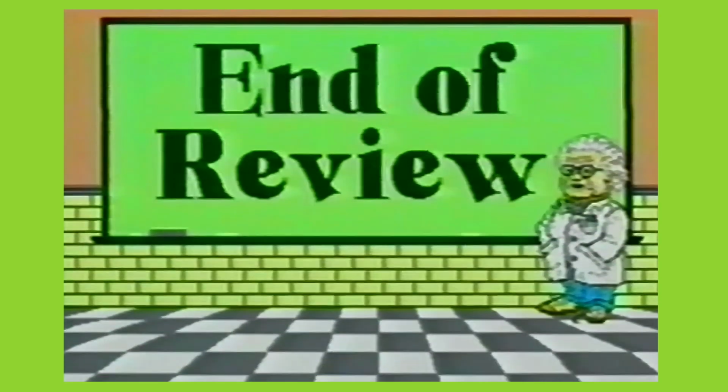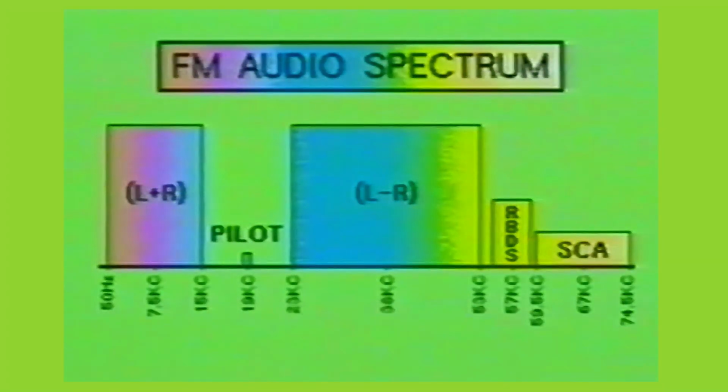The transmitted RBDS information now arrives at the receiver. Receivers equipped to process RDS or RBDS information will contain a special decoder section. The first process of the RBDS decoder is to isolate the RBDS information contained on the FM audio spectrum or baseband from the other program material.